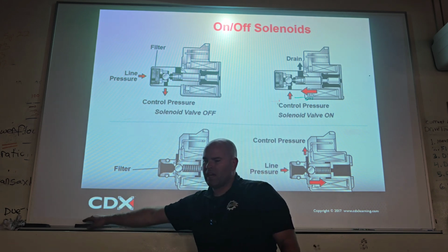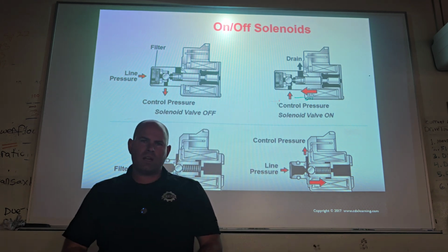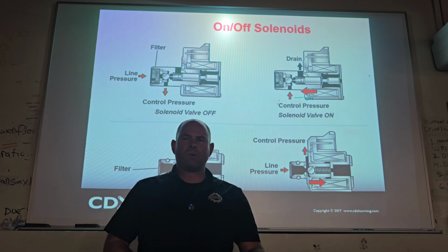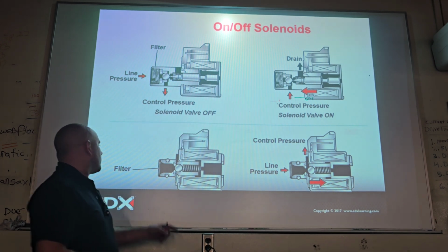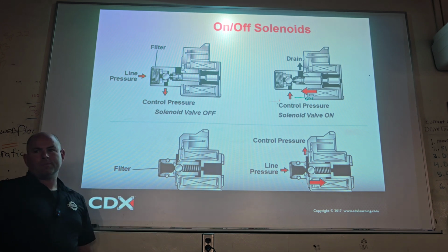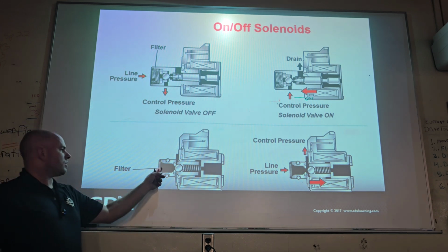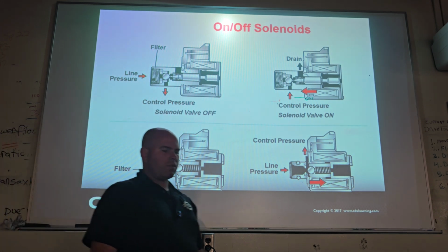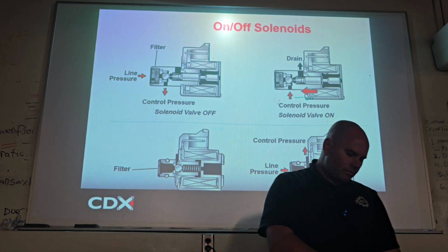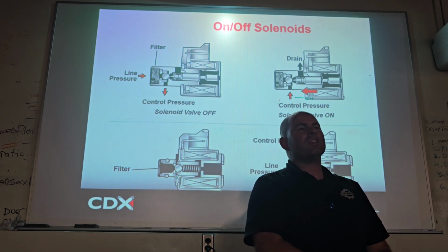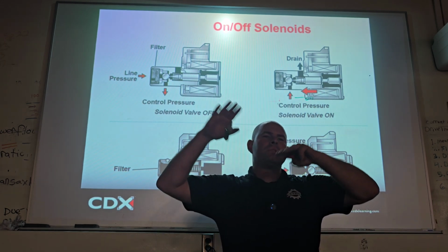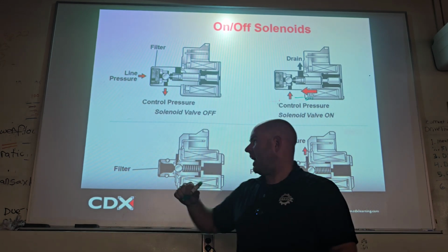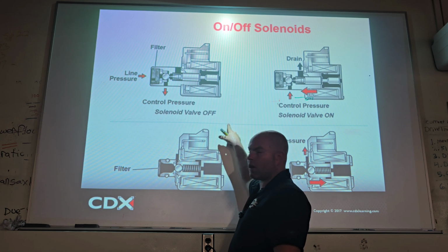Okay? And that, remember, that was for a shift solenoid circuit code, and you can see what the symptom would probably be. Now, there's other things that could happen, because look, what's this? Filter. So what if this filter was all clogged up with toxic sludge from lack of maintenance? Would it set a shift solenoid circuit code? The circuit code is set because it drops a certain amount of voltage or it doesn't. That's for defects in the windings or the harness.